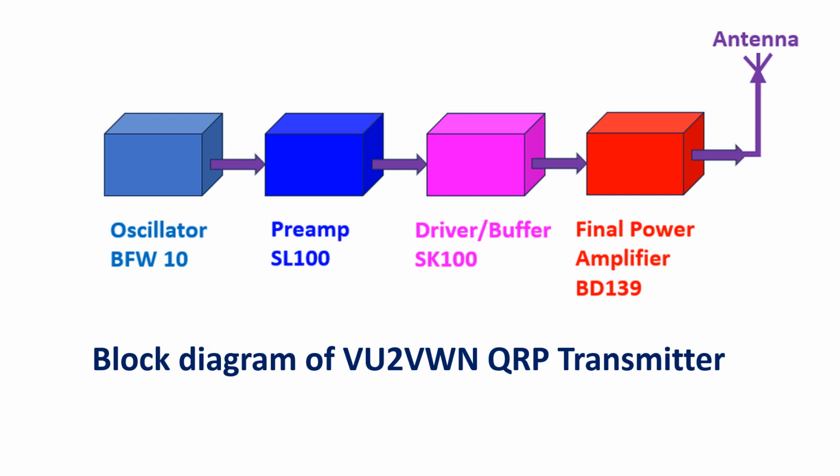Some used to call it a 7/7 transmitter because initial design was for the popular amateur radio band at 7 MHz or 40 meter. Oscillator circuit would run continuously and driver stage would isolate it from the sudden changes in load while keying the amplifier for Morse code DIT and DA, dot and dash. Higher power transmitters would have more driver and buffer stages compared to the simple low power or QRP transmitter.